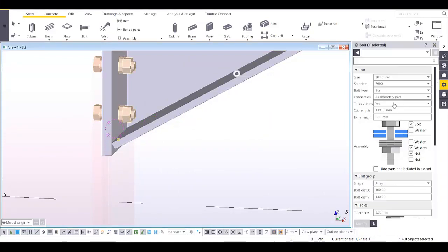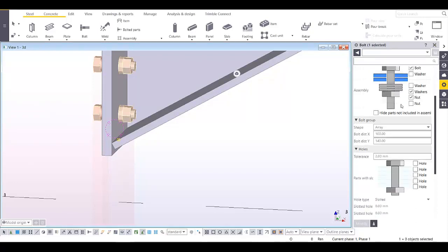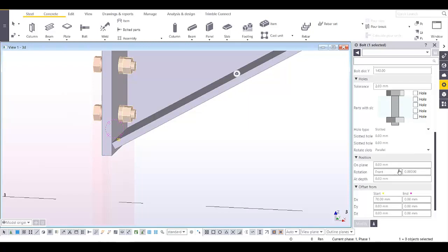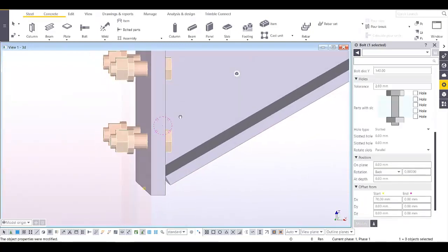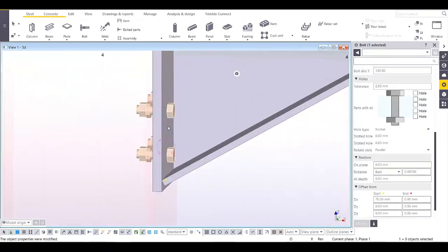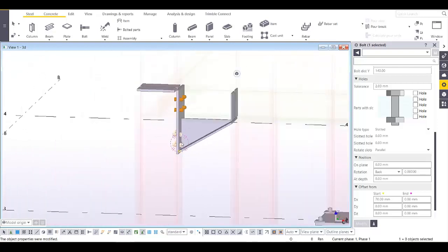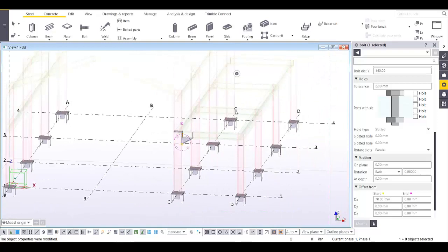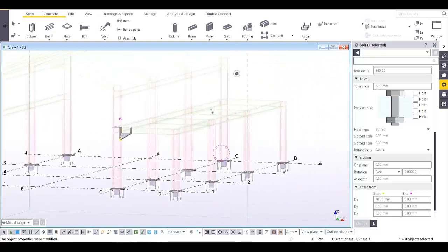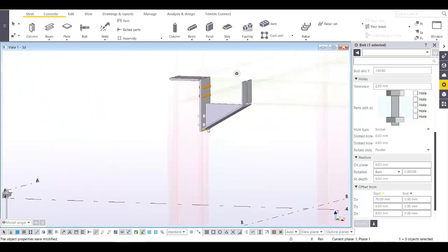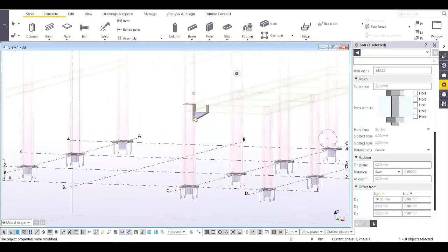So this bolt, I think you can make this one... oh, okay, this rotation, instead of front, I'll make it back, something like this. So in this case, this one is okay. You can easily erect this one, or you can easily tighten the bolt here. All right. So the clash check is not only for the collision of the members, but also for the erection clearance. All right.